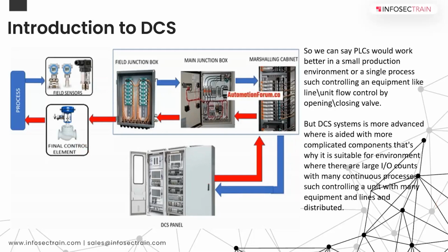The integration of a DCS, FGS, and ESD is called ICSS, Integrated Control Safety System. So what are the major functional requirements of a DCS? Basically control, data acquisition, of course giving alarms, logging the data, and importantly all the historical trends. Of course, that is a separate machine, a separate application, but all this data from the DCS will be used for report generation. Then all the historical data can be stored. If you want to do some diagnosis or improve security, this is where you need to go.